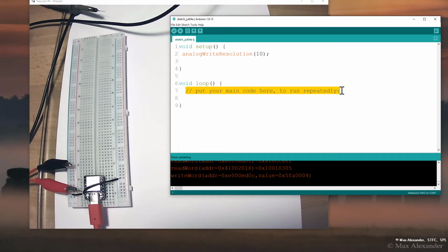We call each of the levels analog to digital units, ADUs. When we type the value in, it's going to be an integer 0 to 1023, and that's going to correspond to output levels of roughly 0 to the voltage rail, which is roughly 3.3, but we measured as 3.28 volts.